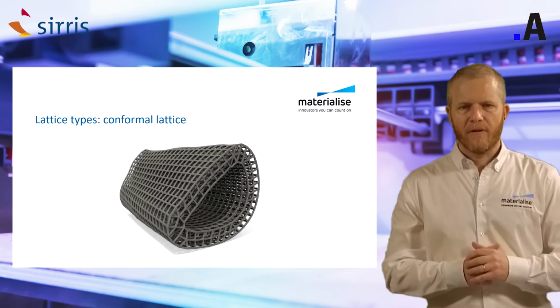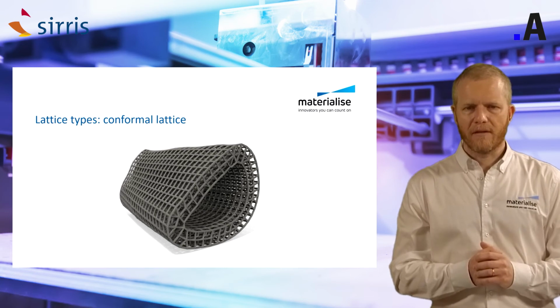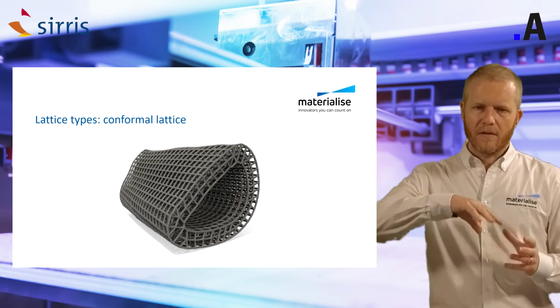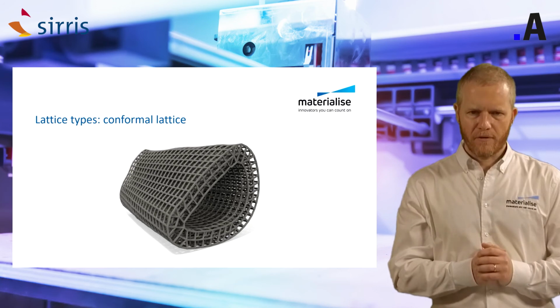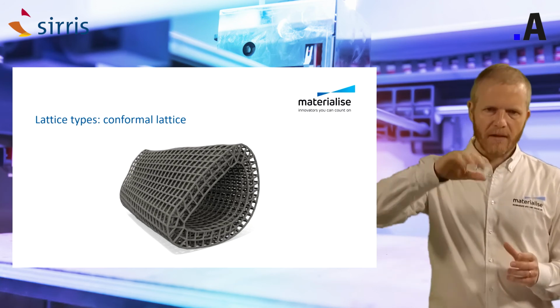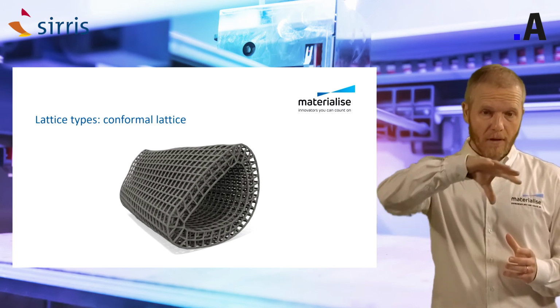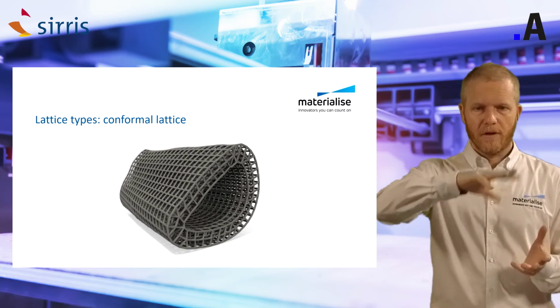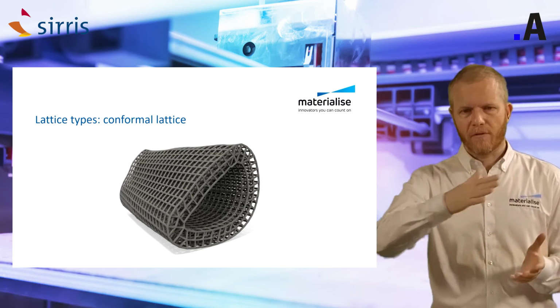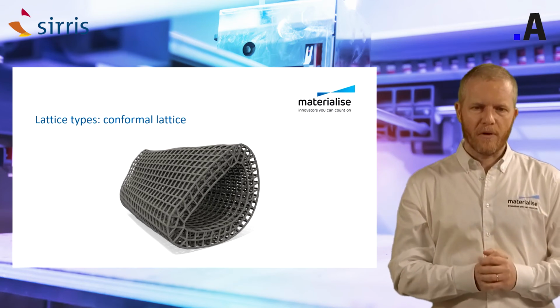Another type of lattice that is available is the conformal lattice. There the idea is that you really follow the surface. Again, you specify a unit cell, and this unit cell will be applied around the surface. Here it's a closed surface, but also if you have an open surface, it will really follow and be conformal with the surface.